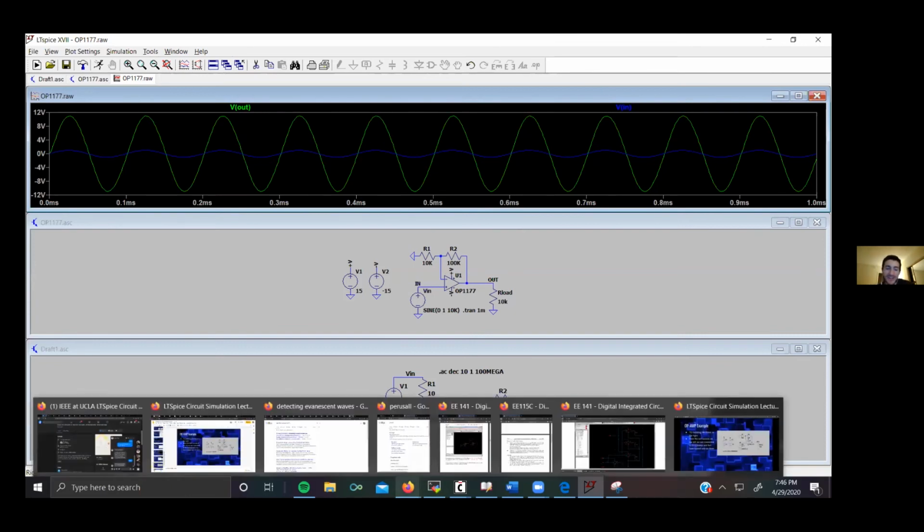Yeah, so LTSpice in general is pretty powerful for circuit analysis. The main drawback though is that if you actually want to create your own components to use in it, it's rather difficult because you have to write SPICE directives for how the component operates based on certain stimulus to the ports. That's a bit beyond the scope of what I actually know in terms of LTSpice, but for general circuit simulation, so for your first order, second order RC circuits, or just normal amplifiers that you might want to try in a circuit, they're very good.